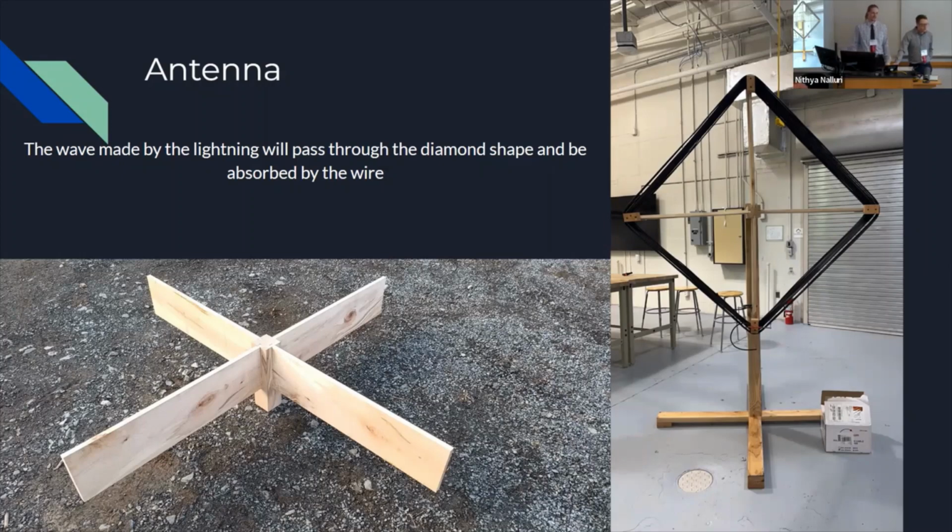The impedance match isn't too big of a deal since we're at such a low frequency. The wavelength is even longer, so with those frequencies, right? Exactly. And even at HF, people have been known to do it, or even VHF, I've heard of people using cable TV coax, it's dirt cheap. It's honestly not too big of a deal because if it has a little more loss, we're not going to have too much power coming out of the antenna itself. Not only that, but you're not running a lot of it, I'm assuming. Yeah, and it's a thick cable, so the loss is small anyway. Makes sense?